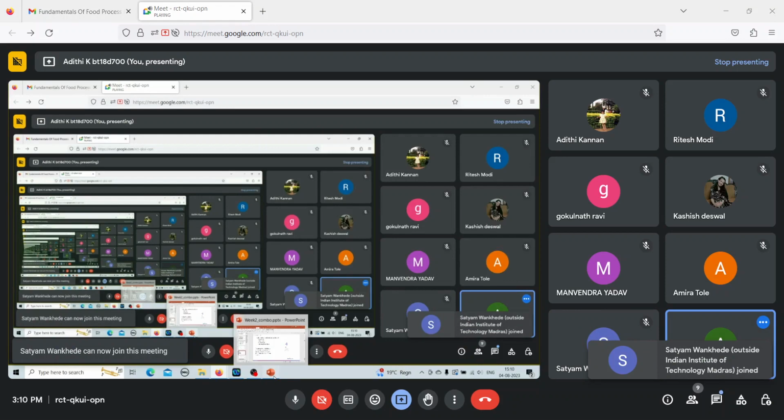You have a spring and dashpot, which each describe one particular behavior of the fluid. Now, how the spring and dashpot are arranged will give you different kinds of models. Some models will arrange them in series, some will arrange them in parallel, and some will arrange them in a combination of series and parallel. Each of these models best describes certain classifications of viscoelastic fluids, which is what we will see in the upcoming questions.